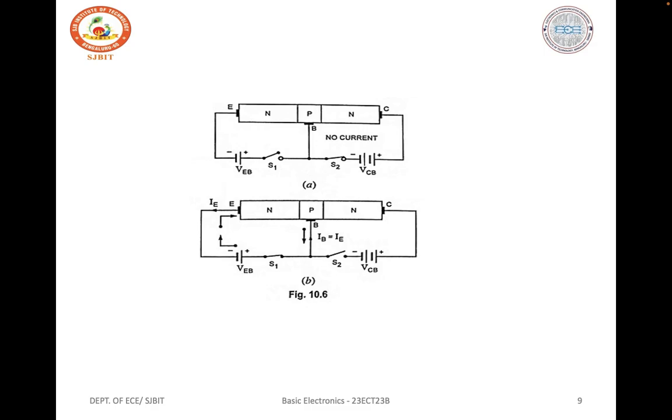So coming to some of the BJT voltages and currents, the terminal voltage polarities for an NPN transistor as well as the conventional current direction. The direction of the arrowhead indicates the transistor bias polarities. For an NPN transistor, the base is biased positive with respect to the emitter and the arrowhead points from the base to the negative emitter. The collector is then biased to a higher positive voltage than the base.